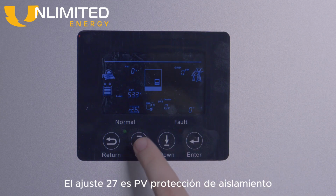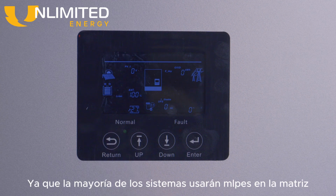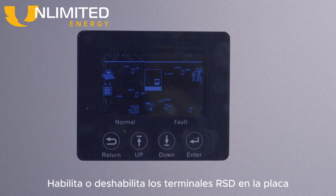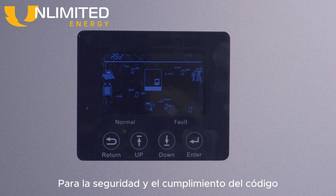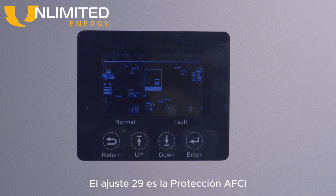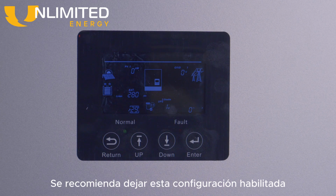Setting 27 is PV isolation protection. It's disabled by default as most systems will use MLPEs on the array for code compliance. Setting 28 enables or disables the RSD terminals on the board. This is enabled by default and should be wired to an external shutdown button for safety and code compliance. Setting 29 is the AFCI protection, which is enabled by default. It's recommended to leave this setting enabled.